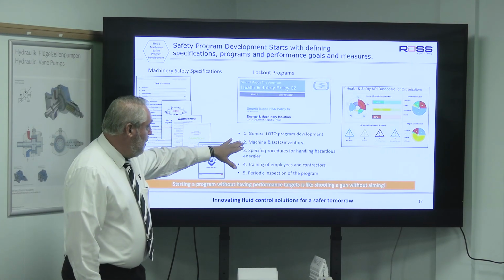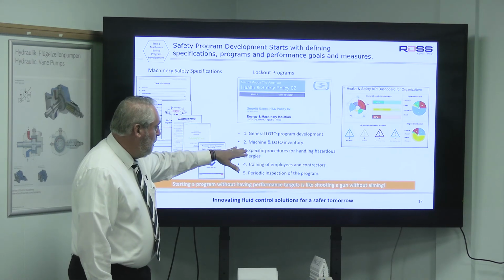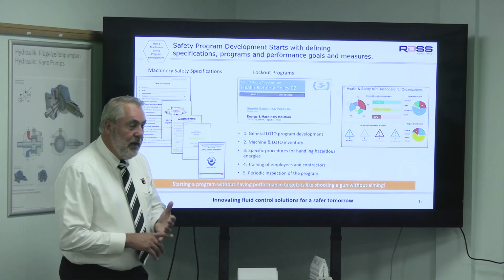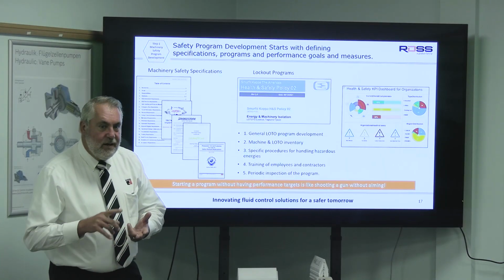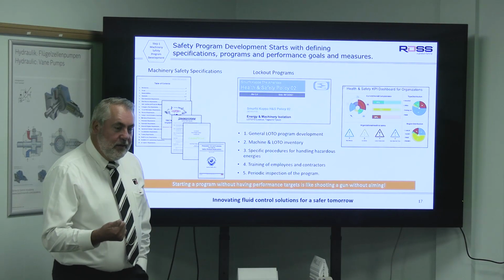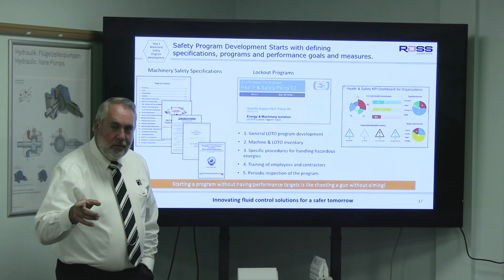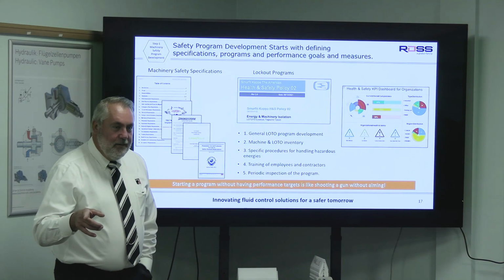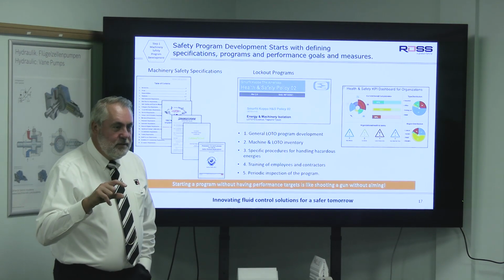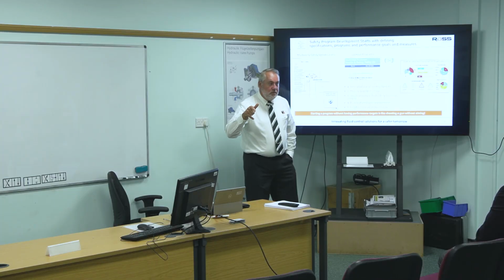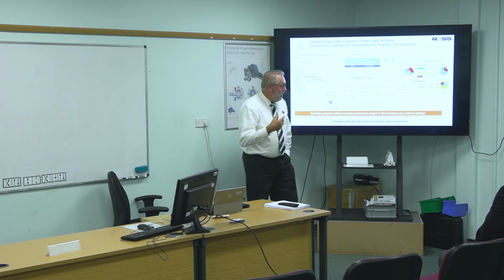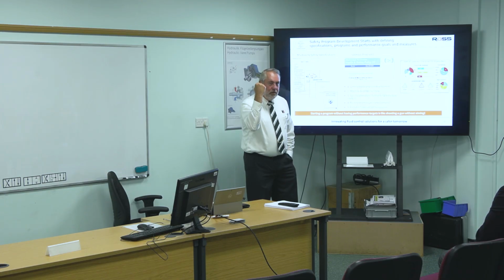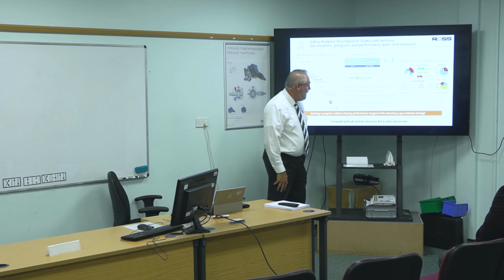And it started off with doing a machine inventory, developing specific procedures for handling hazardous energies, and that's hydraulics, pneumatics, electrical. And a lot of people think, I just shut that ball valve off or I turn the pump off, I'm at zero energy. Problem with that, a lot of your pumps will have check valves right in the pump. As soon as you shut the pump off, check valve closes, now you got stored energy. And you've also got this thing called gravity. Sometimes it's pushing down on a load. You turn the hydraulics off, you turn the air off, things might fall. So you have to think about things like that.